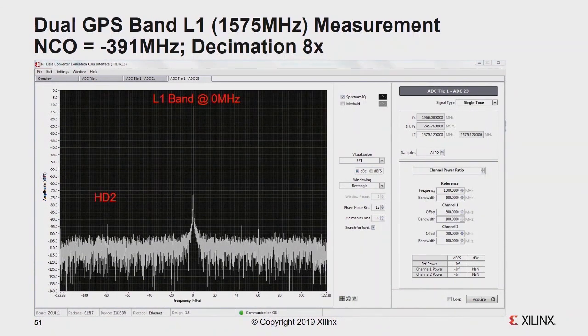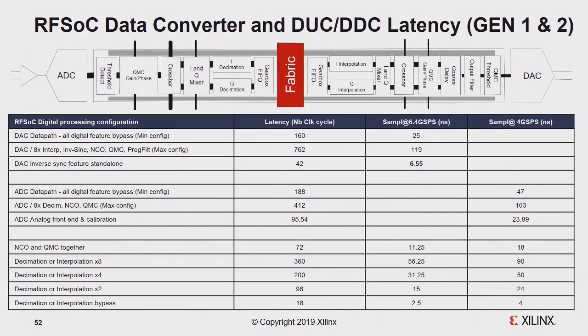So the filtering and then the processing is improved. And one more thing, you can see our frequency originally is 1.9. Right now it's only 122.88 because it's 8 times less. So you can save your resources for your other implementation on your FPGA.